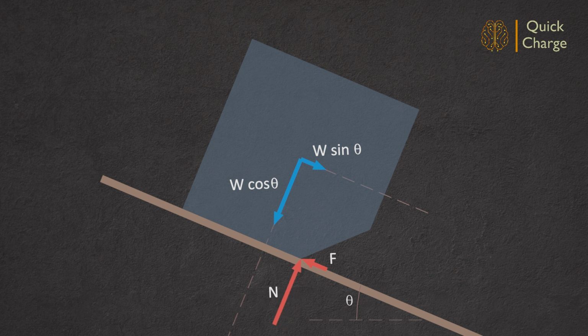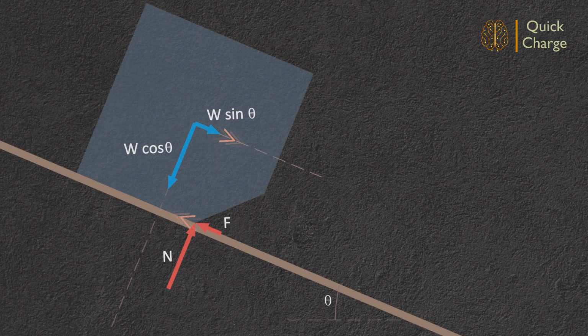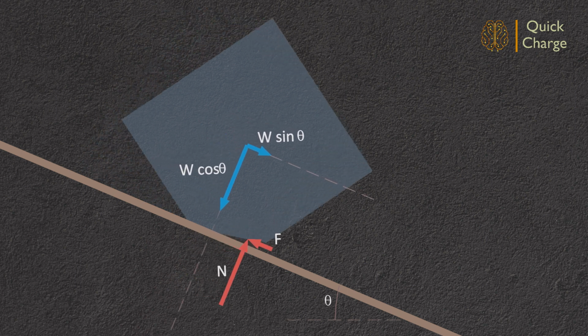Again, summation of forces and moments are zero and the object is in equilibrium. Any further increase in slope results in increased magnitude for the parallel component of the self-weight. The frictional reaction also will be increased as the limiting static friction is not reached. However, as the line of action of the normal reaction cannot be moved further away, there will be a net overturning moment in the clockwise direction, which results in tipping of the box.